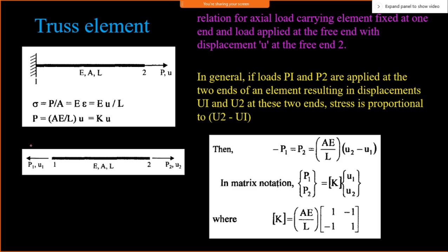So if you look into the truss element, this is also called a bar element. The truss element means I'm going to orient this and give a deformation in the x direction and y direction. I'm going to convert whatever axial deformation into x as well as y. Actually, the deformation is only one axial deformation, but because of this orientation, I need to determine the deformation in x as well as y. That is a transformation technique we have seen and we use.